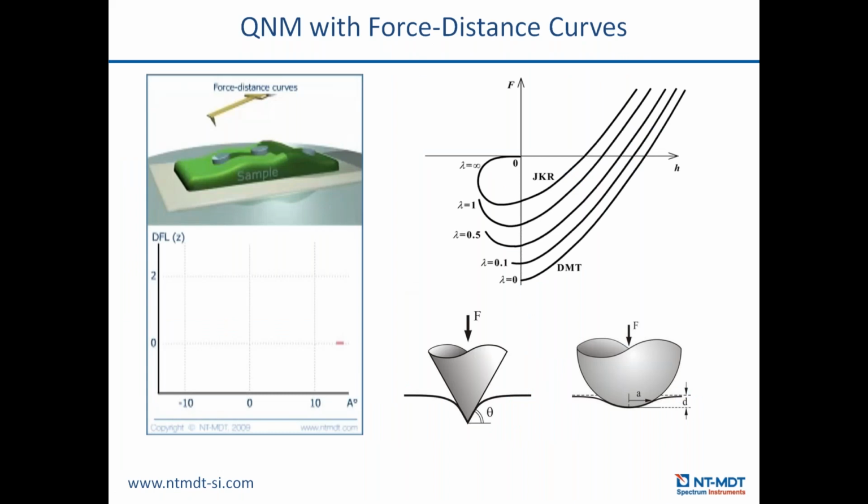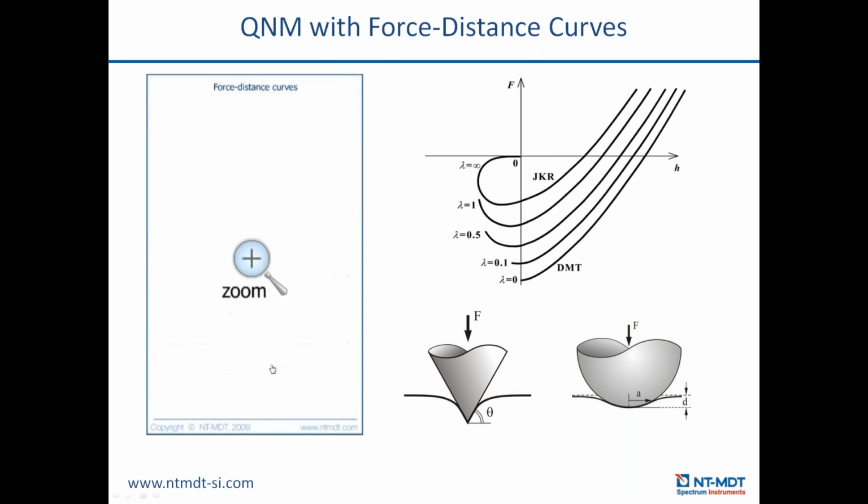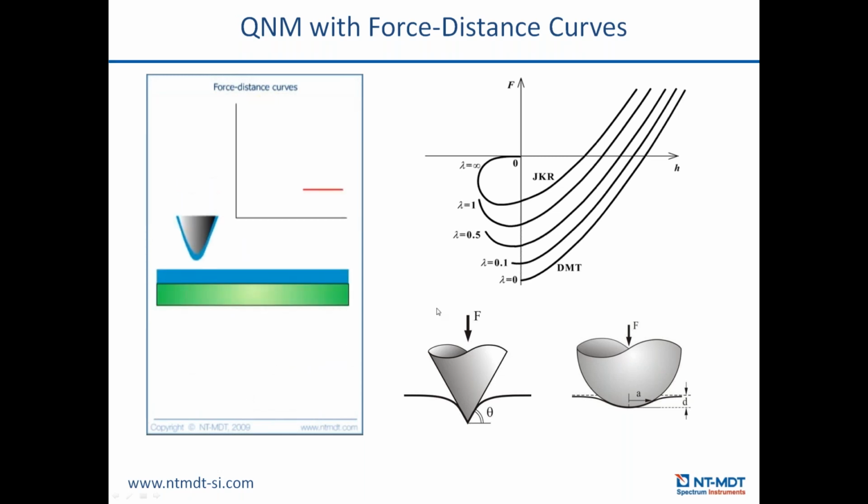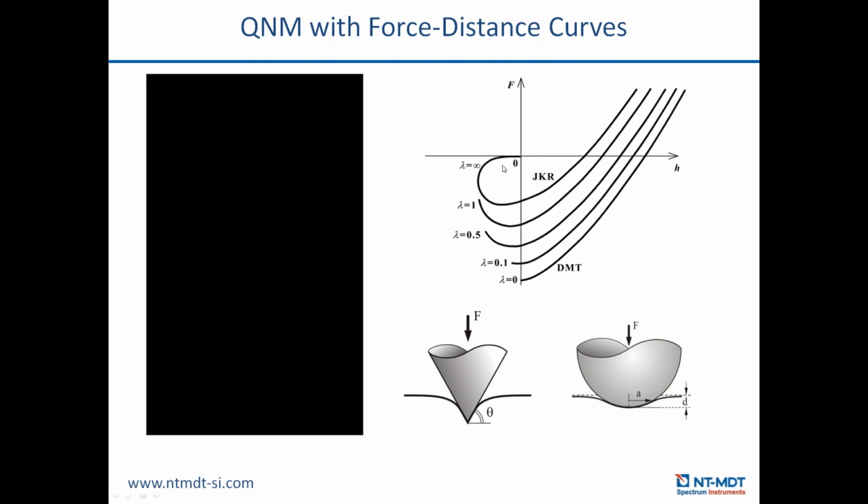The next technique I want to talk about is so-called atomic force spectroscopy. Let's see how it works. We have the tip, and we vary the distance between the tip and the sample, probing it at different points. Depending on the mechanical and adhesive properties of the sample, we get different kinds of so-called force curves. Applying the algorithms and apparatus of contact mechanics, we can extract quantitative data from this. This is called quantitative nanomechanics.